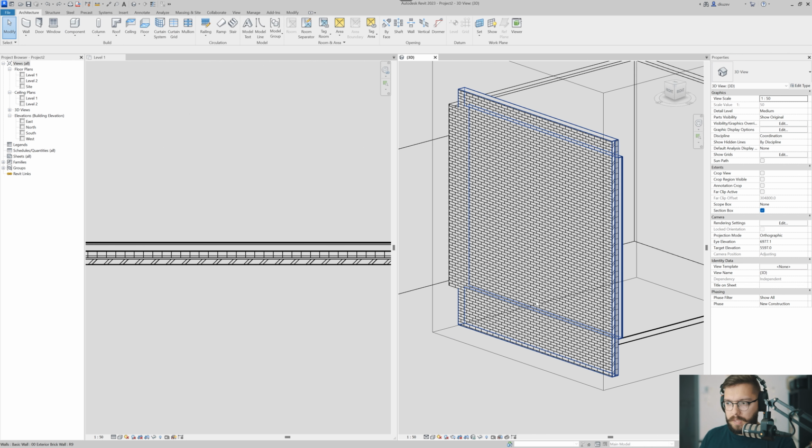All right, now let's move on to something called wrapping, okay? Wrapping is Revit's ability, or your ability again, to manipulate certain layers within the wall every time you place either a window or a door, or there's some kind of an interruption within the wall, okay?